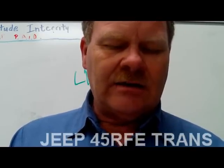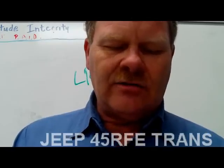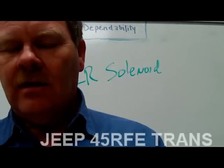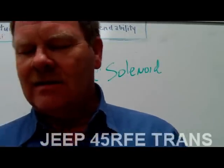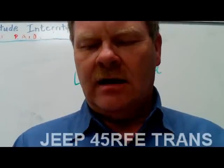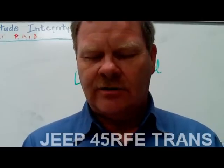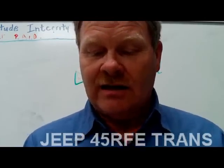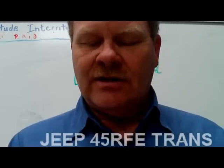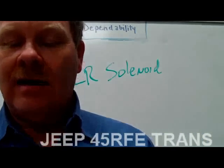All right, mechanical and electronic components as well as TCM inputs. You put the electronic and mechanical operation together. It works like this. The TCM takes inputs into account to determine what gear the transmission should be in. The main factors affecting the shift schedule include gear selector position, input speed sensor and output speed sensor readings, and the overdrive off switch. In other words, if you turn off the overdrive, it's going to be different. Also the throttle angle from the throttle position sensor, and the temperature inputs from the transmission temperature sensor, the ECT sensor, and the battery temperature sensor.